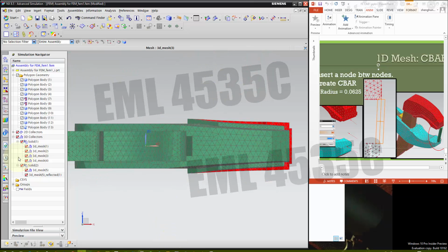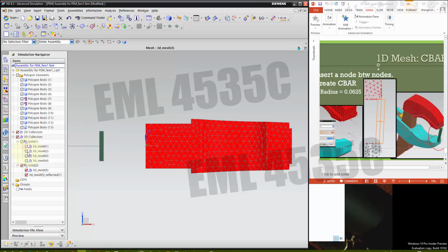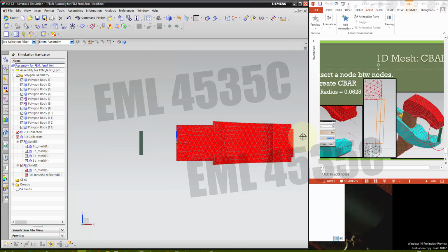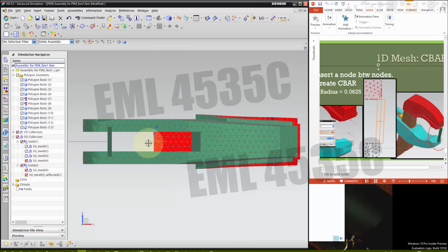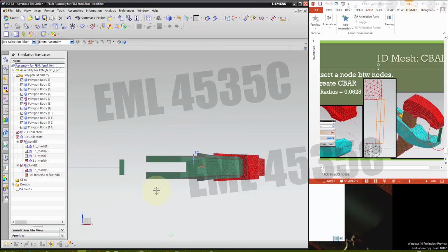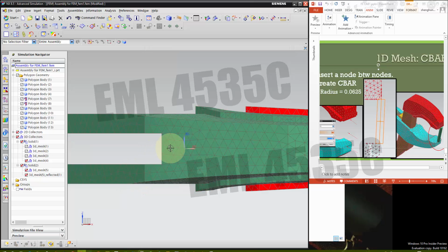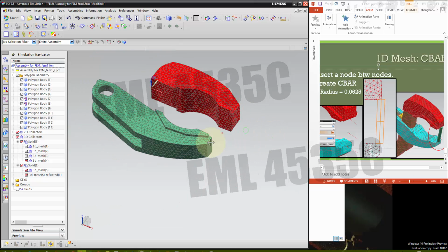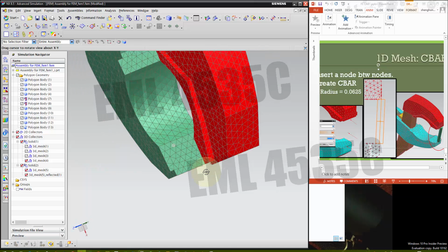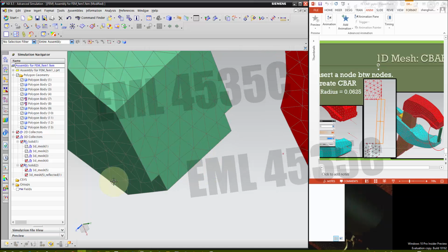The lower jaw. Okay, we'll find the lower jaw. That's the lower jaw. The red one is the top upper jaw. The upper jaw is perfectly symmetric on the XY plane. There's a line here. And the lower jaw is not. We rotate off a little bit. You can see in the middle, the mesh does not really stay on the symmetry plane. That's why we did a half and half for the upper jaw. But somehow we got lucky. This node is right on XY.